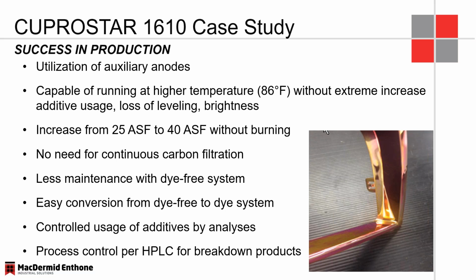What the 1610 and 1600 allow you to do is to try, if you really are having issues with pits and dirty tank walls and anode bags and really having to run carbon continuously, trying the 1610 is really such a low risk, because if it doesn't work, I can easily just add the dye to that system, and it essentially becomes the CUPROSTAR 1600. So there's a lot of flexibility in there to see if it works based on the application.